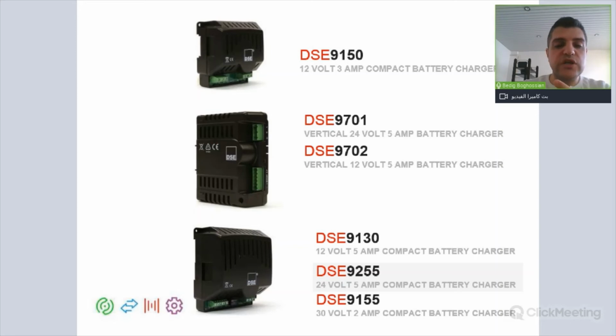With the overcurrent protection, you don't worry about the cranking, because when you start the engine, you know that the starter draws a lot of current from the battery, and that could cause an overcurrent on the charger, or could cause a voltage drop across the batteries. But the DSE charger detects that and switches off the output to protect itself.